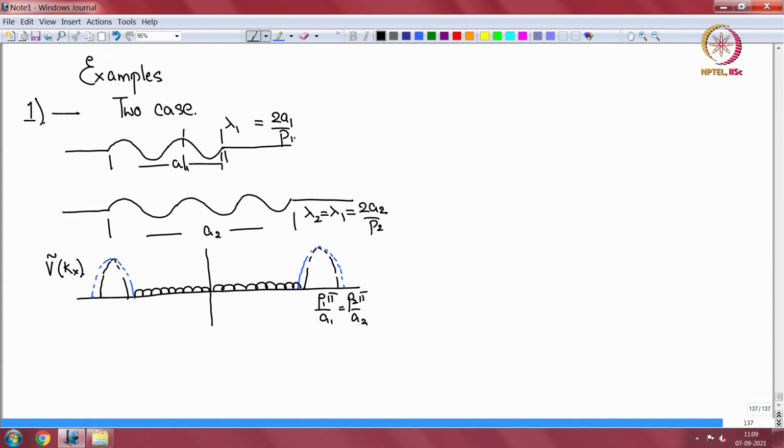So if I excite both the panels at a certain omega equal to omega 1, which leads to a k1, and it is less than these wave number values, that means below coincidence of that mode, then the k1 line can be put here, and this will be the minus k1 line, and the integration limits will extend between minus k1 and k1.